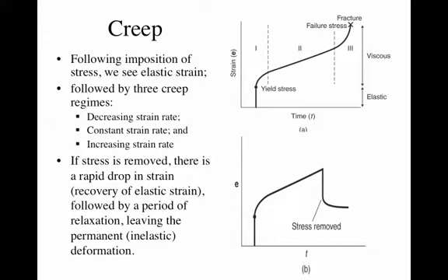If the stress is removed, there's a rapid drop in strain in the lower diagram. And then we see a recovery of elastic strain followed by a period of relaxation, leaving a permanent inelastic deformation, so it doesn't return to its former state.